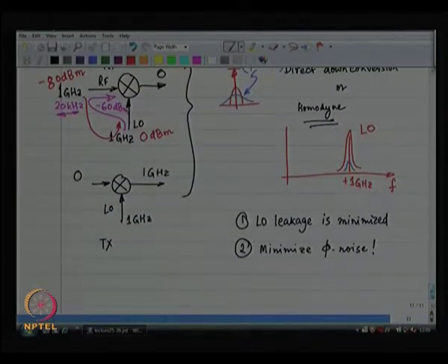Okay. The only time when the RF can actually leak into the LO and create a difference is at the transition edge. At that edge, if RF happens to leak into the LO, then I get some problems. Then RF mixes with RF and creates double the signal, the square of RF. First of all, RF is going to mix with RF with attenuation.